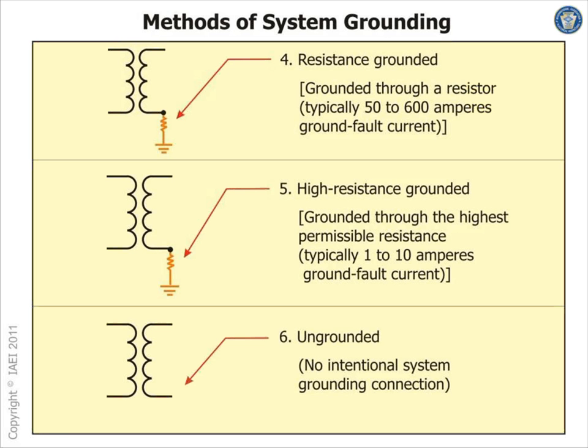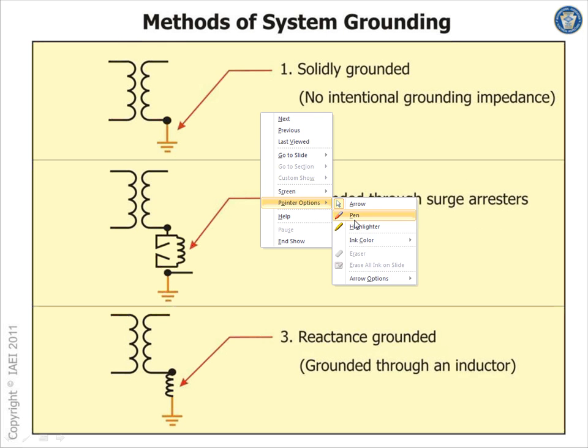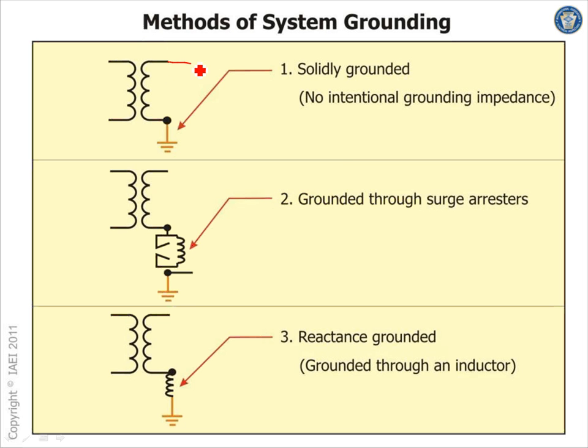It's called a surge protective device, and you install it on a grounded or ungrounded system. So if I have a system like this, and I grab a surge protective device, you typically bring it from here. You put it right here on the phases, right? And you go from here to the ground, if I'm drawing it right.